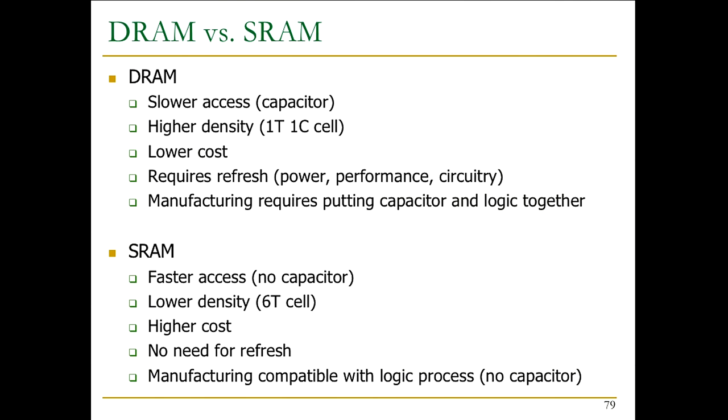People try to place these things in almost a hexagonal manner, such that they optimize the area that you get. So things are not exactly next to each other. That also changes the capacitive coupling effects significantly. So people do a lot of tricks to make sure that the density is very high. And that's what's making it harder and harder to manufacture DRAM.